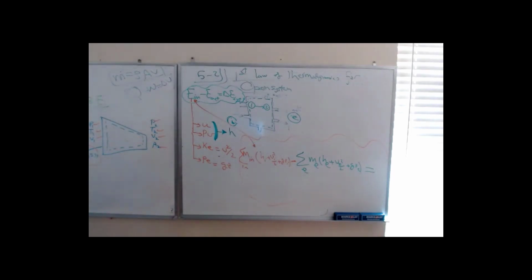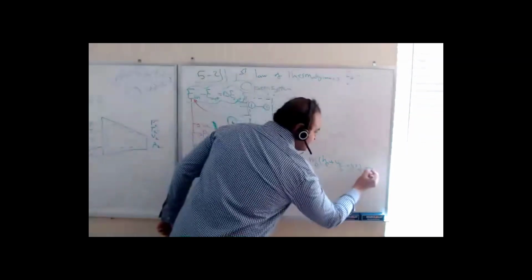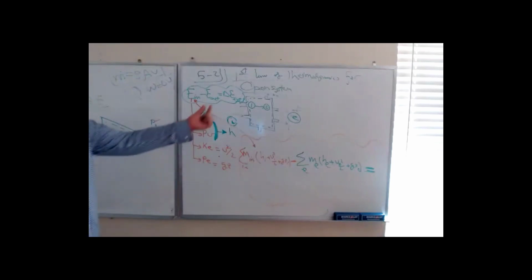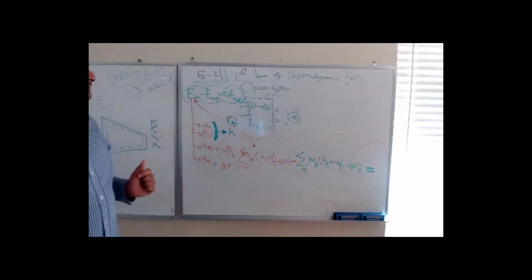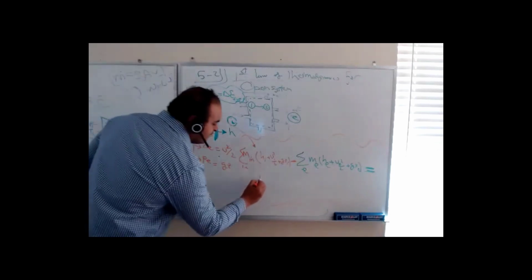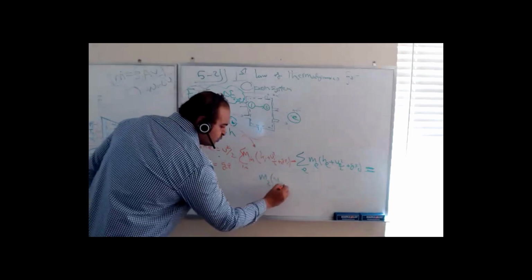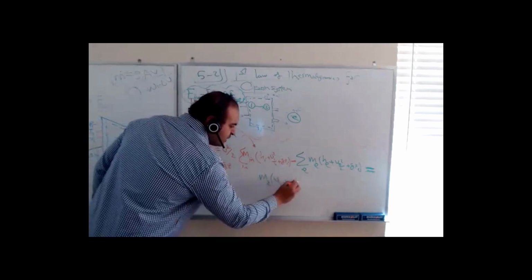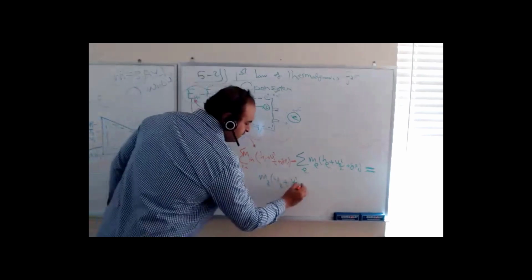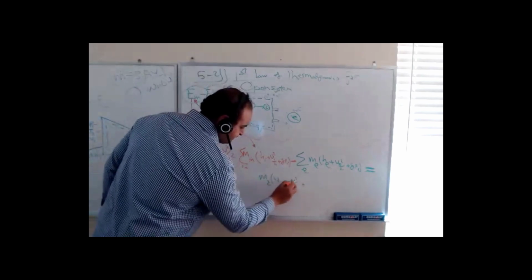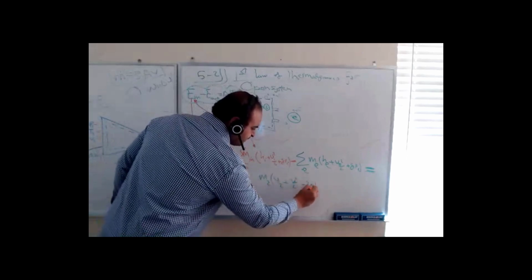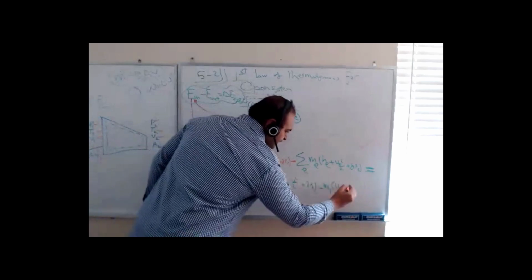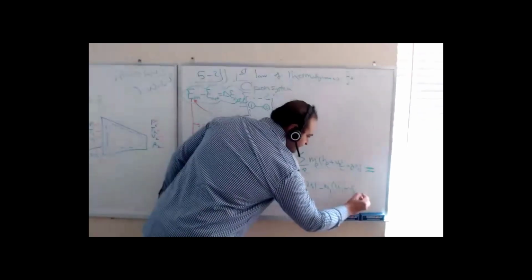Okay, guys, equal what? Somebody tell me what this is. This input minus output equals what? A change in energy within the system, which is m2 (u2 plus V2 squared over 2 plus gz2) minus m1 (u1 plus V1 squared over 2 plus gz1).